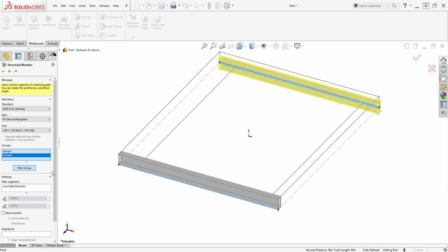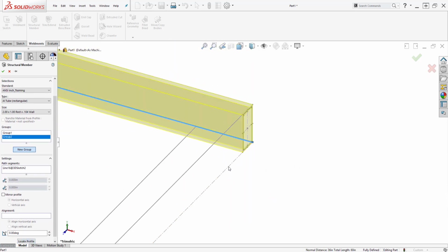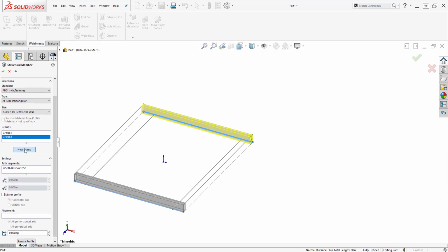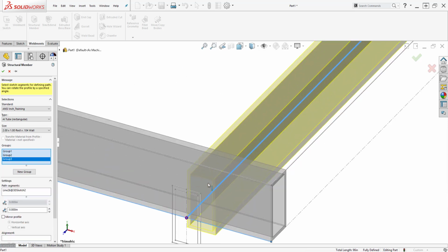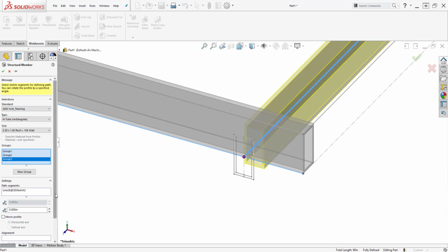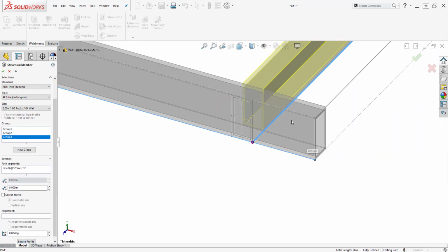I am adding and locating my tubing based on the existing skeleton. Make sure to leave 3 inches between the perimeter and the wall of what is going to be the drive rail. At the end, I'm going to choose to trim this tubing to open up the wheel well so that we can go up ramps easier. If you leave this alone, this is what I consider a protected wheel well.